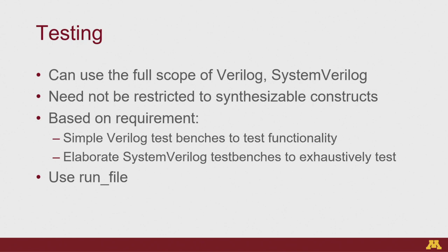So what that means is that in Verilog, or rather in SystemVerilog, once you have the FIR, how do you know whatever you designed is correct or if you made a mistake? That's essentially where a test bench comes into play. A test bench's entire goal is to see whether the logic works without caring how it works, if that makes sense. Say you have a very complicated filter which does a lot of operations, or you have some kind of a communication protocol which needs to send out packets and has a lot of pre-processing to do.